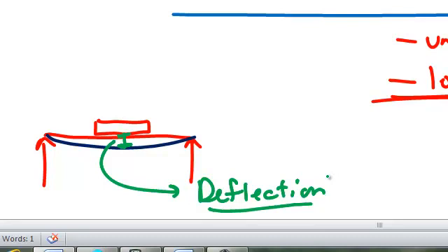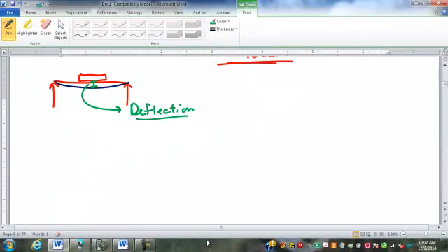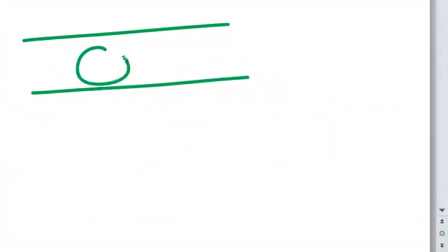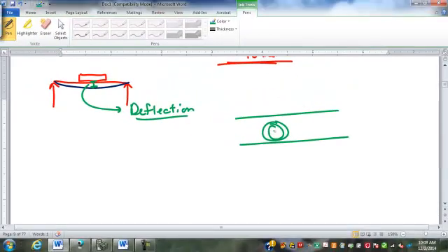The problem is, in construction, when we're using this in a building, there are other systems that depend on those structural members, not just the support of the rest of the structure, not just the support of the building. You have mechanicals like your ductwork going through, holes drilled in your joist for the ductwork to go through. You have wires and plumbing going through there. If one spot is flexing 3 or 4 or even 1.5 inches or 2 inches, the ductwork's going to get kinked or bent or separate, or the plumbing's going to get bent or damaged. Wiring, probably not such a big deal, but you still don't want it being pulled and stretched a lot.